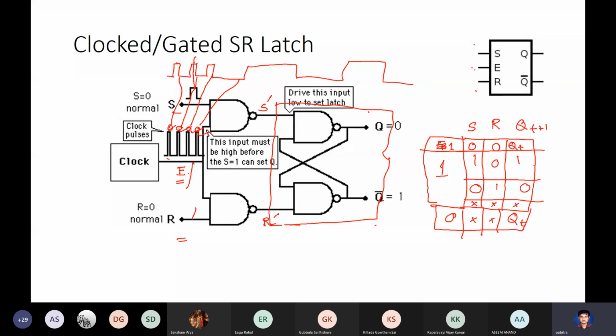So I should keep the latch on for an amount of time which allows for the delay in a single gate. That much. So the clock width should be more than the delay of a single gate, so that it has a tolerance, it allows this time to change the output, but it should not be staying on longer than that because I want only one operation per clock cycle. And that's done. I'll wait for the next clock cycle for synchronization. Make a change.